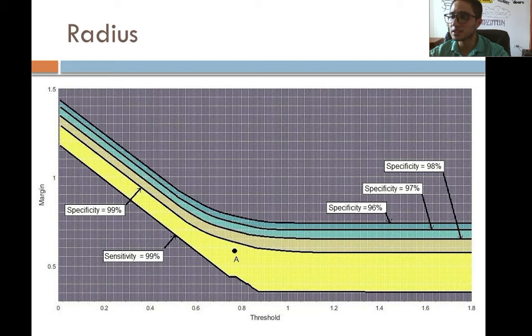For sensitive systems, it is recommendable to use two models, one with 95% specificity, for example, and another with 99% specificity, to classify the results in three: negative, doubtful, and positive. However, we can draw the specificity curves with only healthy motor data, obviously, and set up an arbitrary value. Then select any margin and threshold near the middle zone, and that's it. We can find the model with no faulty motor data.